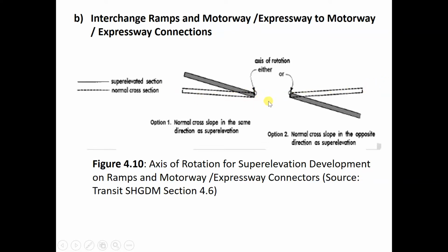It's sloped inside. Apparently the drainage is in between, in the median, so it slopes inside. And for the right lane, you slope from the right hand side of the road inside as well. So it will rotate upwards for the left hand side, and then go downwards on the right hand side. So this is a central rotation at the edge, just the edges of the road next to the median. This is the median.